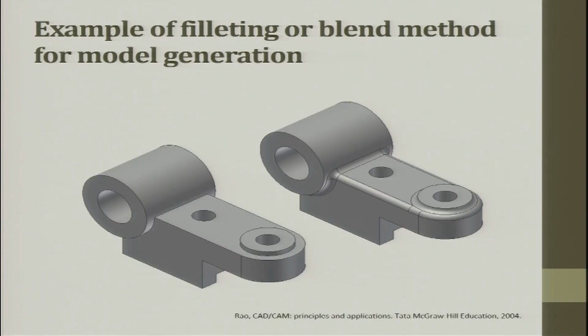So, when we draw these objects in real time, we can have a simple primitive. These primitives are chosen and placed at locations. But when these primitives are placed and butt against a flat one, it is always necessary to have a filleting done such that these points are not the stress concentration points, and you can keep continuing this.